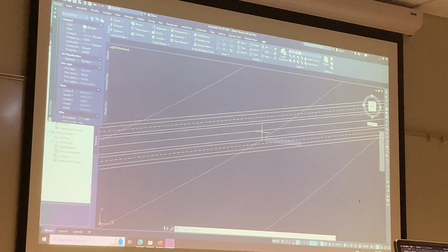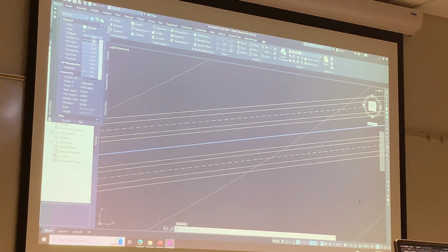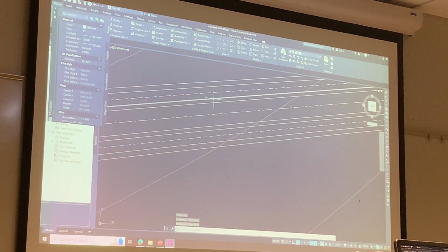You want to make sure you're editing the properties of that. Which line type did you click? For these, I just do dashed, and for the center line, I would use center. At a scale of 20. I mean, that's not really required. When you say scale, you're talking about the line gaps, the line type scale. Yeah.